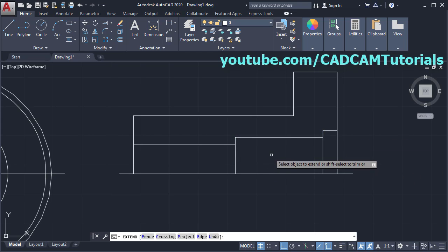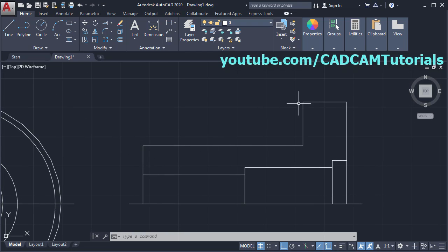Then press enter. Then here we need a chamfer of size 2. For that, click on this arrow and click on chamfer. Then click on distance and specify the first chamfer distance as 2. Enter. And the second chamfer distance will also be 2. Just press enter to accept the default value. Then we want to chamfer multiple times. Therefore, click on this multiple option. Then select this line, this line, this line, this line, this line, and this line, and press enter.